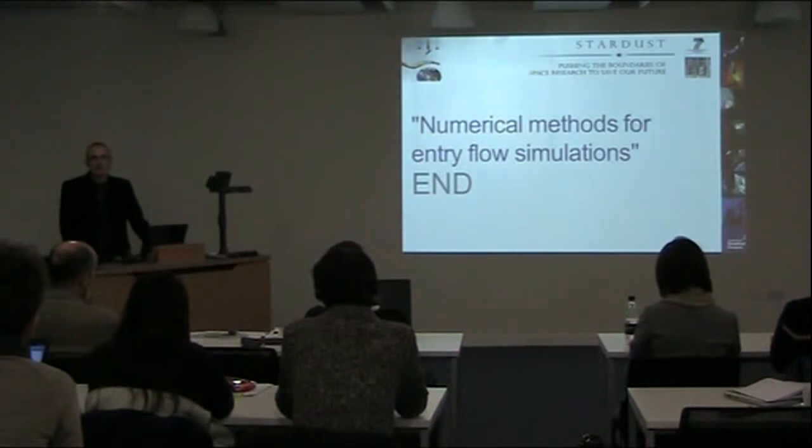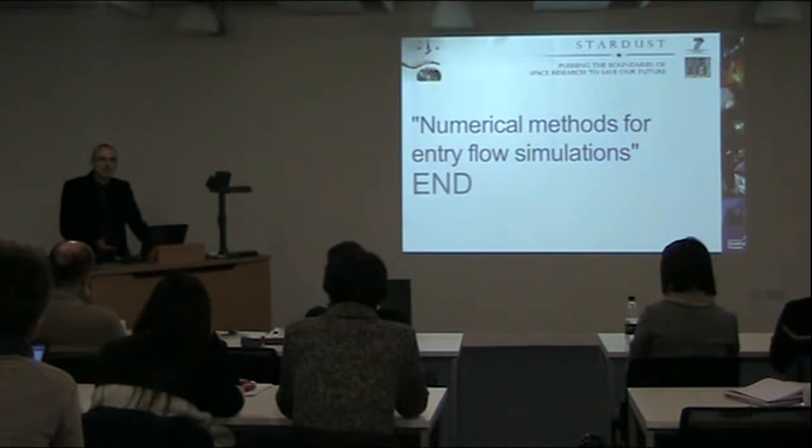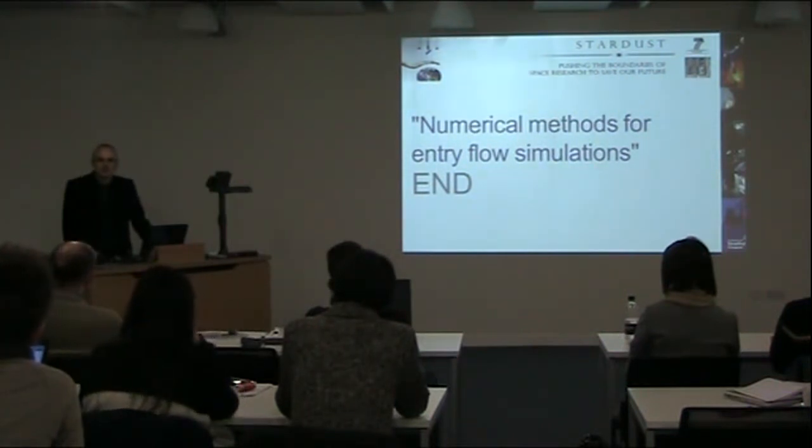But the fact is that structured meshes usually give better results. So there is always this trade-off. It is extremely difficult to build a structured mesh on a complex shape; it could take weeks or months to build. An unstructured one could be a matter of days, and it is almost automatic. It's just computer time, while in the other case, it is human time.